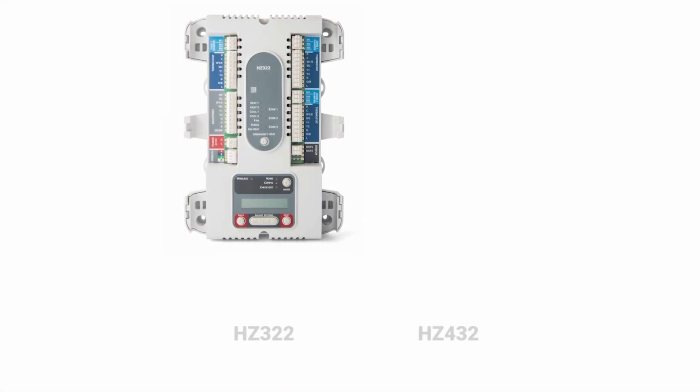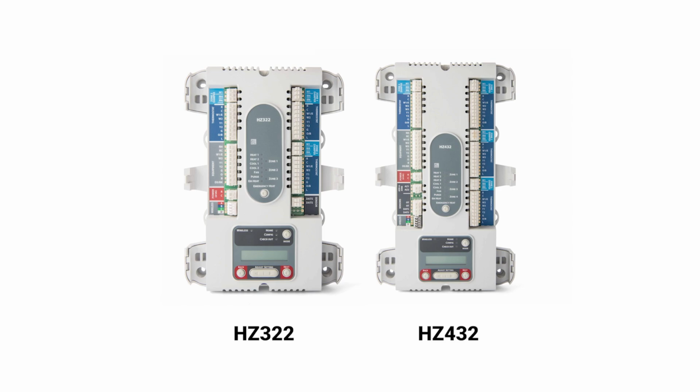Once enabled, the Calling Zones thermostat will control staging for heating and cooling. The HZ322 and HZ432 will control staging from only the active zone, which works especially well in systems where one zone consistently needs more or less conditioning than others.